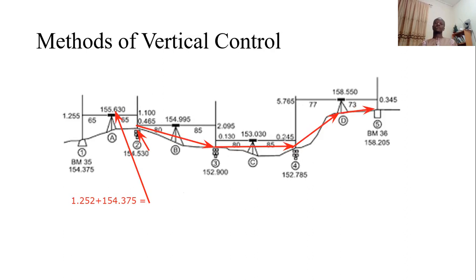So we would have transferred the height to another point to be used. And then with that height, now we can relate to the scheme, the design by the architect or by whoever it is, and whatever project that we are on. There could be a value. We need to put a bolt at a certain level. Then we can do that.